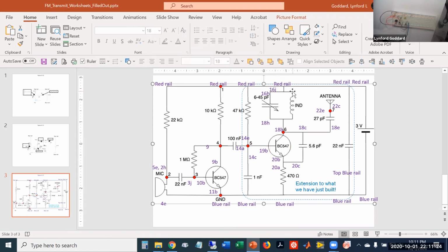So I want to go between 16 and 18 on the upper half. So the inductor is this part. In the past, we used to use a coil. The coil is a relatively cheap way to realize the inductor. You have to play around with the geometry of the coil, like the number of windings and the space between windings and so forth to get a specific value. This gives us a guaranteed value for the inductance, so it's much easier, but this is actually one of the most expensive, or it is the most expensive component of all these.